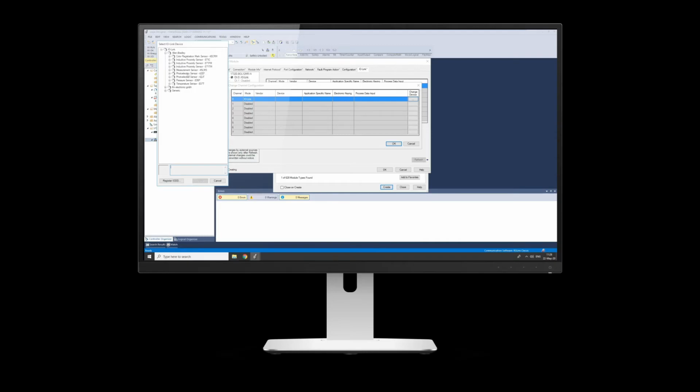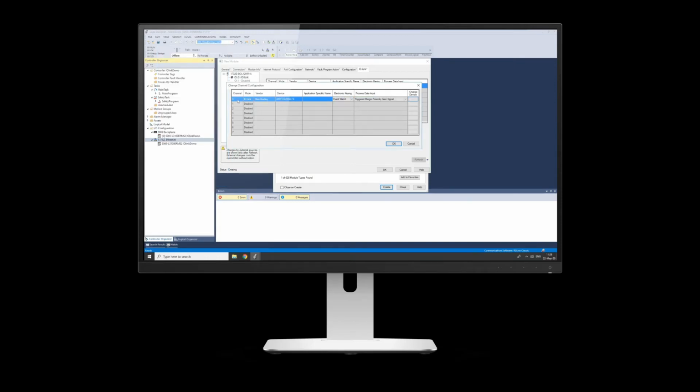For this example, I'm going to add the 42EF sensor that we have. So if I go to photoelectric sensor 42EF, and mine is a D2J back, which is that one there, version 1, and it's an F4. So 42EF DJ F4. That's my photoelectric sensor. Click create, and then it's added into the project.